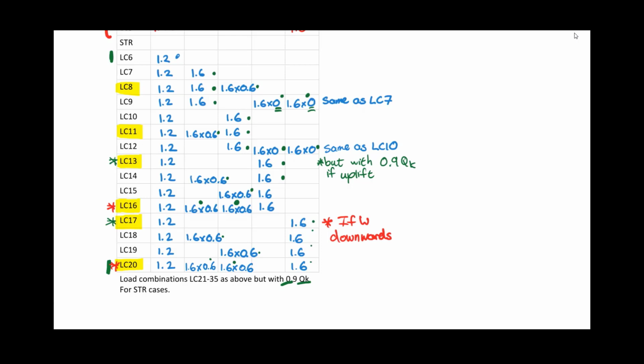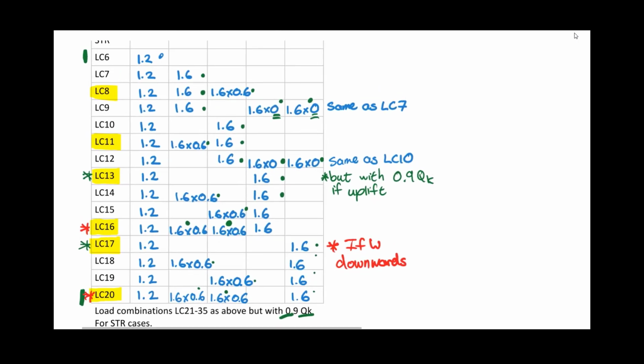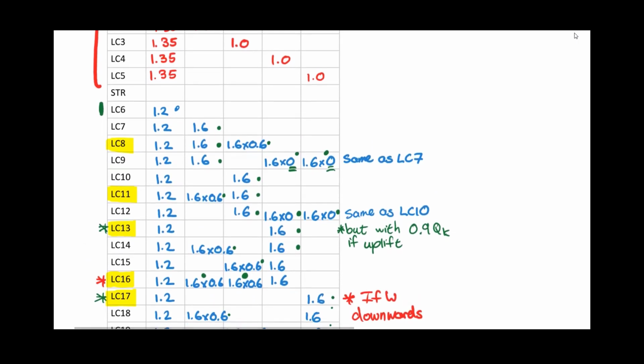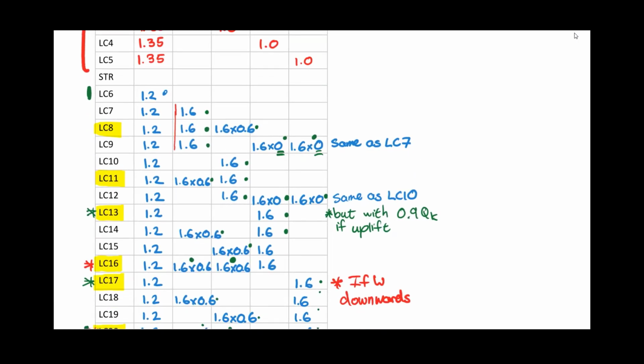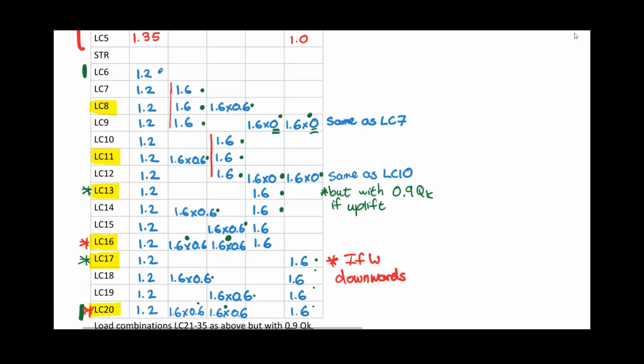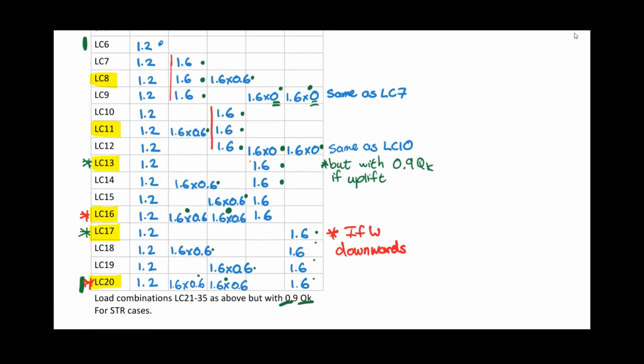So that takes us through generating a set of load combinations for the structure, and then how to identify the potential worst case ones. And just to highlight what I mentioned earlier, we took one imposed load at a time. So either it was the first imposed loading, or it was the second imposed load leading, or it was the wind load leading, or it was the other wind load leading, and then we combined it with everything else.